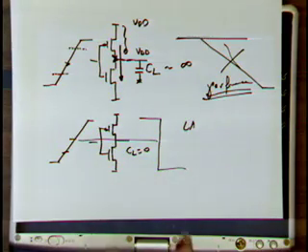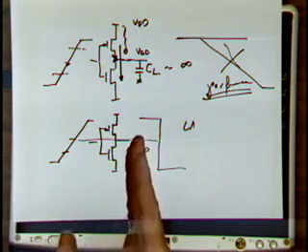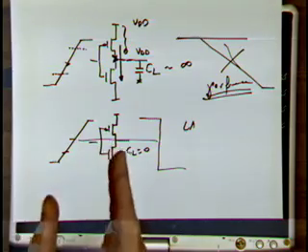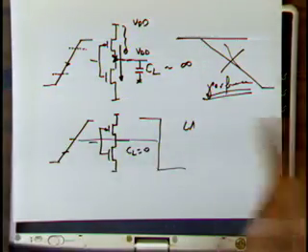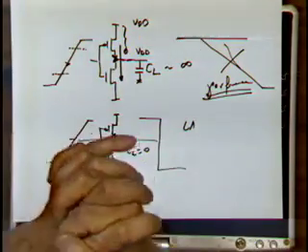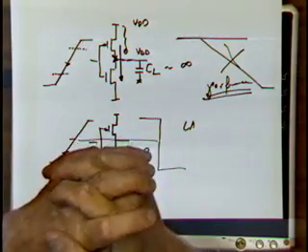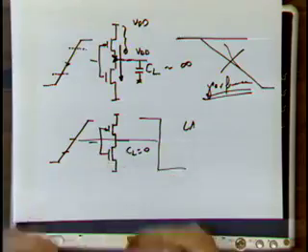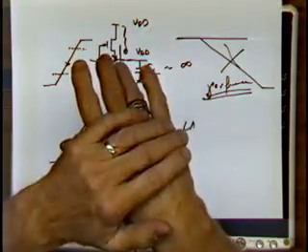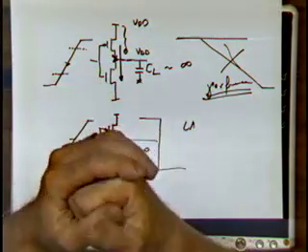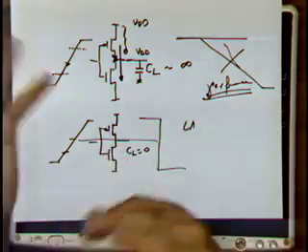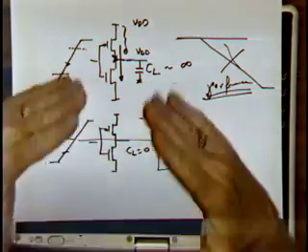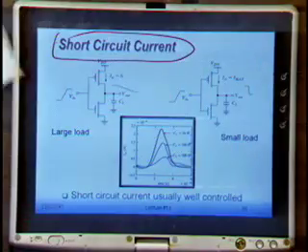So if you design your circuit in such a way that your slopes are basically identical for input and output, the max amount of power that's going to go into short circuit current is about 5%. I'm willing to pay that. 5% is a small number, so that's what we live with. Larger than that is not very good. Okay, 3 to 5% is what I can play around with, and the way you do that is by using slope engineering.